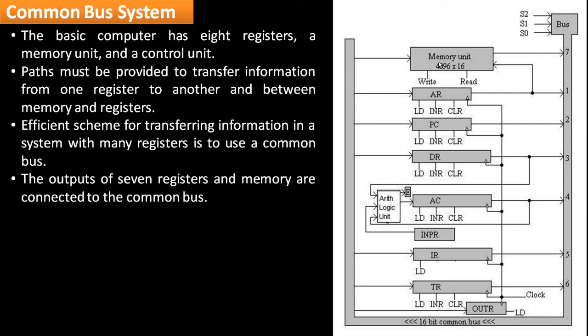All the registers, memory module and others are connected with the clock as seen here. The memory unit has a write-read signal, and it also has a bus from where it can give out data into the bus system. Also it can accept data into the memory module from the bus. So the memory module will basically have the data bus, the address bus, and read and write.